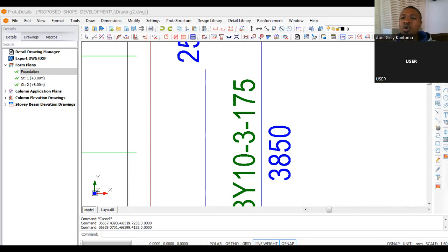Okay, so all you need to do is just to specify the height. It is not in your position to make provision for height. It's based on whatever is given to you from the architectural drawing. The height of building varies. It depends on whatever the architect must have used. When it comes to warehouses and workshops, most times the headrooms are always higher, so you don't assume a particular height. You use the height that was given to you by the architect.